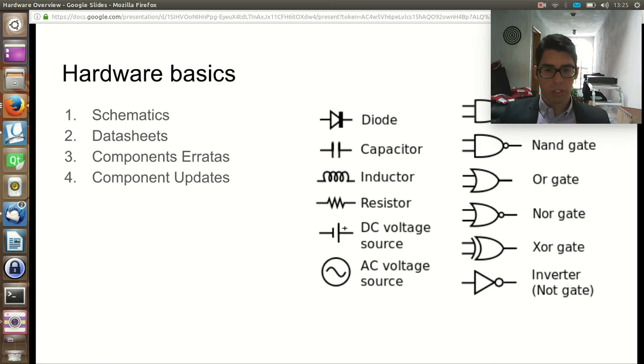These documents will give you a heads up of any issue regarding the way the device operates, and updates in the components. You might have a data sheet with obsolete components, so you might have some problems. Periodically check the dates of the components, and that will save you the frustration of chasing a problem that was fixed in an updated data sheet.